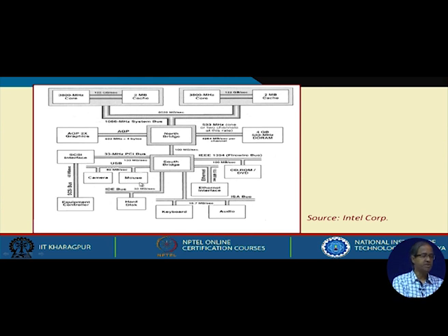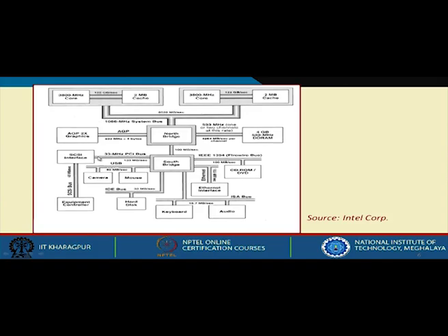Now the point to note is that in modern systems, as the standards have evolved, this USB standard has become more and more widely used and faster. So, there are USB versions which instead of being connected to the south bridge, are connected directly to the north bridge because of their much higher speeds. So, architecturally this is what exists inside a CPU motherboard, and you can see there are so many different buses, and each of these buses will have their protocols, their rules. We are not going into the detail of all the buses; rather I will try to highlight some basic concepts which will be common to most of these buses.